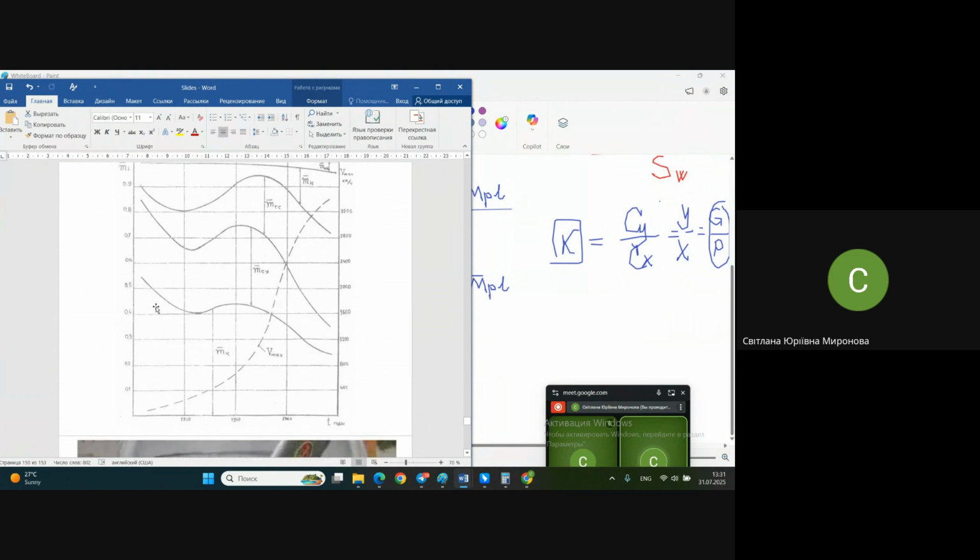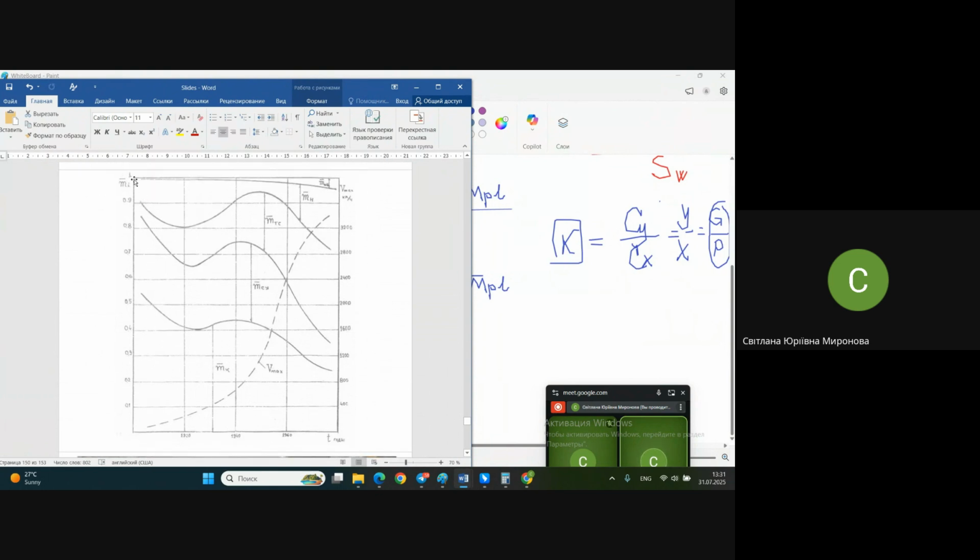Here it is like addition, and the whole vertical axis is the whole takeoff weight, you might say, which is equal to 1. And each space between curves is the relative weight of one or another system of the aircraft. And what we might see, here is the structure weight, the structure of airplane. That weight of structure is changed with reducing gradually.